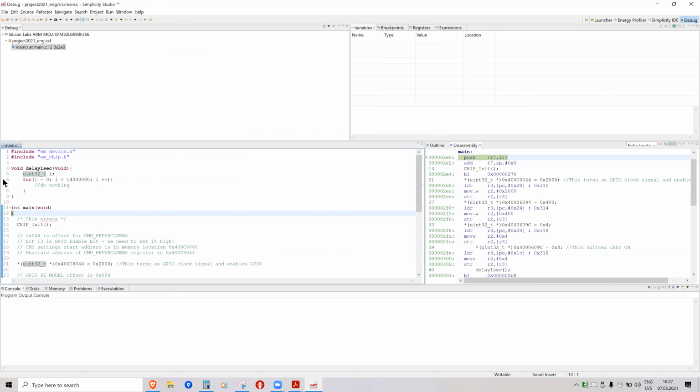So maybe the breakpoint is right here. Let's put the breakpoint on line 6, because sometimes when you create a variable, the compiler sees that the created variable is only used locally. So the variable is not actually created, but a register inside the CPU core is used to store this variable. So this line number 5 actually never executes.